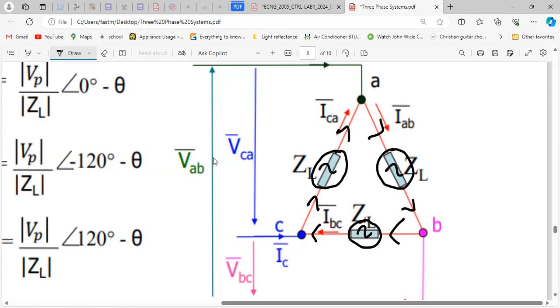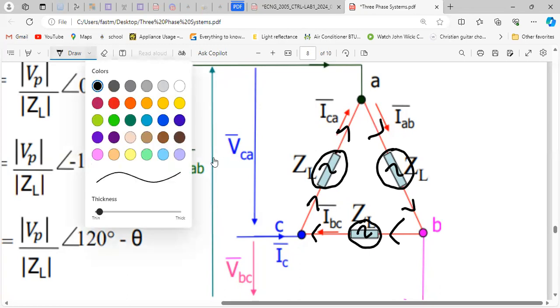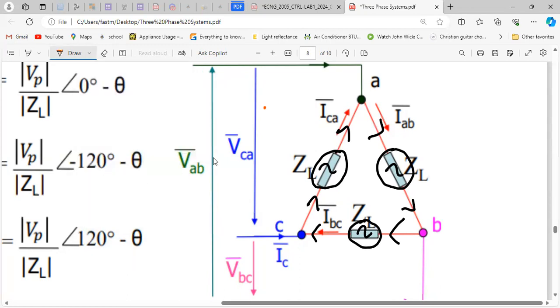So from this here, because the delta is with respect to currents, right? And the three phase currents, yeah, so this one here is A, this is B, and this is C, just like your star. It's not going to change, but it has no neutral. And we know for the delta, the voltages are the same, right? So therefore, the current is the thing that will change.